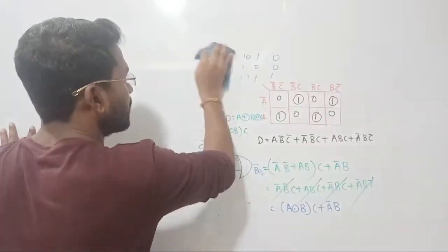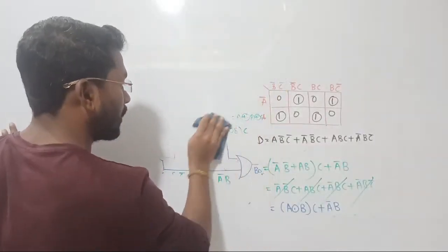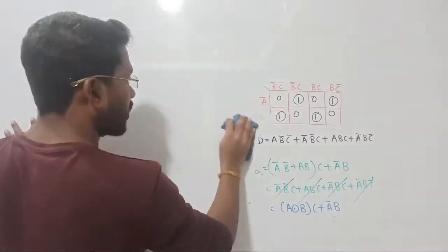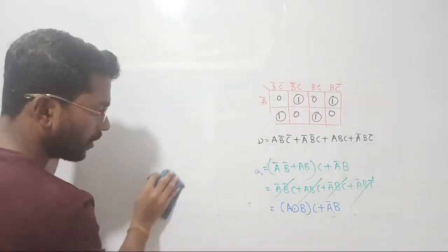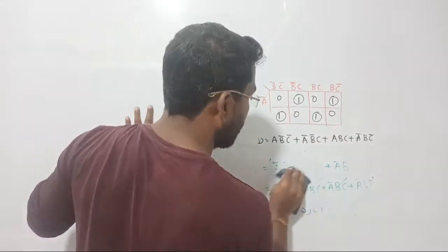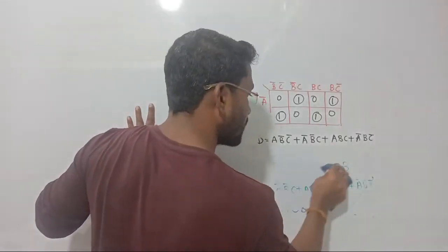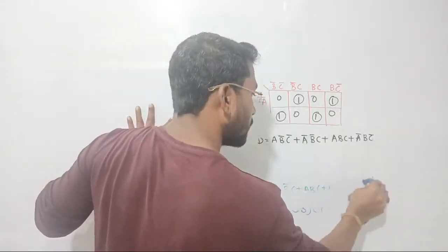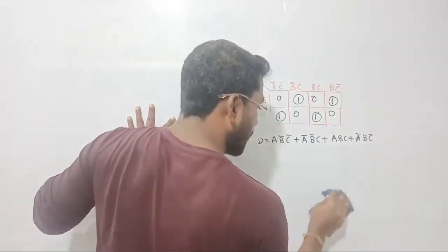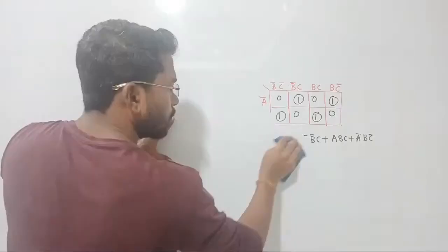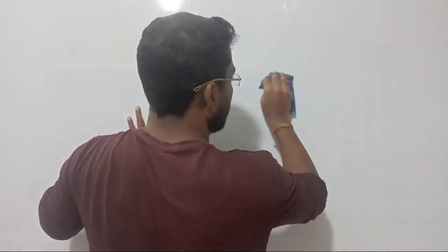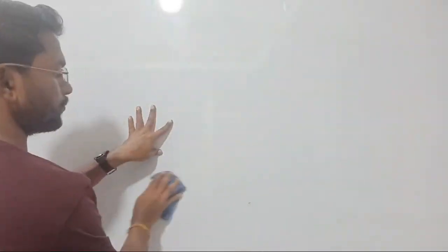So our next task is to design the parallel adder circuit, right? So let us do that one. Take the parallel adder, right? So keep the heading, we are going to design the parallel adder circuit. Okay, now what do I mean by parallel adder? Parallel in the sense that full adder circuits are going to be connected in parallel, right? So full adder circuits are going to be connected in parallel. You can also use half adder circuits, that's our wish only, right? We can also use half adder circuits, right?